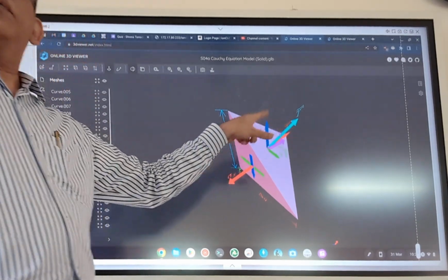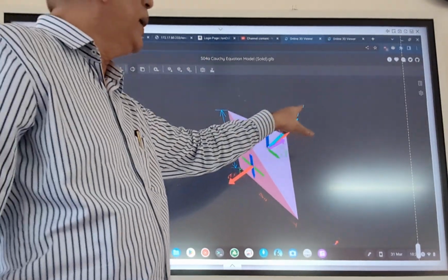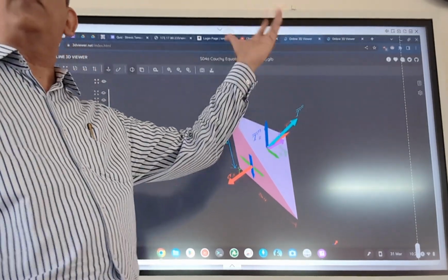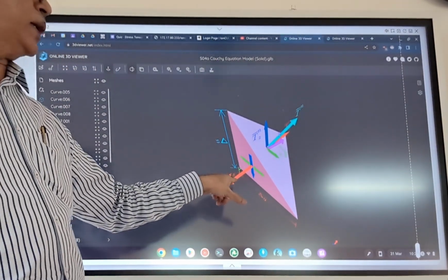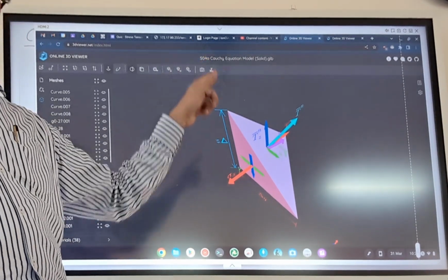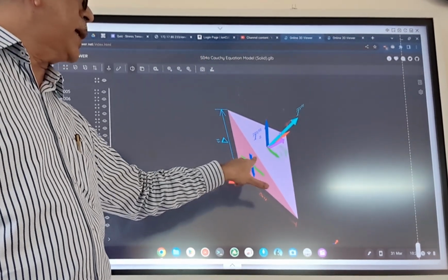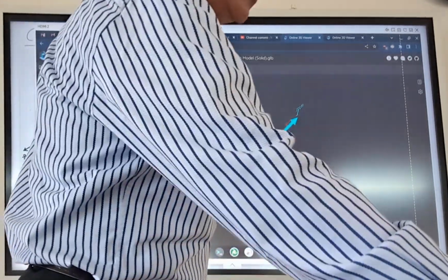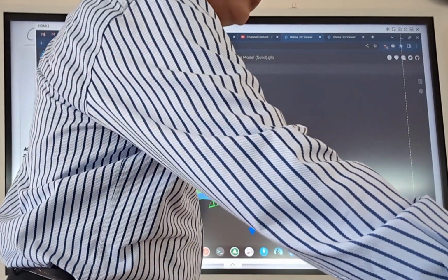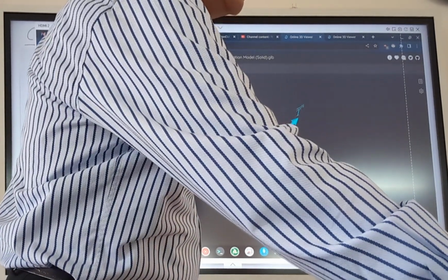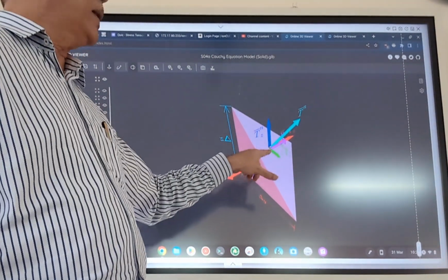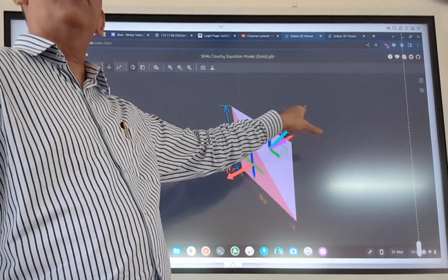The traction vector which is unknown on this plane is Tn bar. So Tn bar is the traction vector which we want to find out. What is known to us is on the x plane, y plane, z plane, those are the three triangular faces. So this is the x plane, the other one is the y plane and the z plane. So once you know the traction vector on the three planes, you know the stress state at that particular point. Based on that, you should be able to calculate Tn bar.